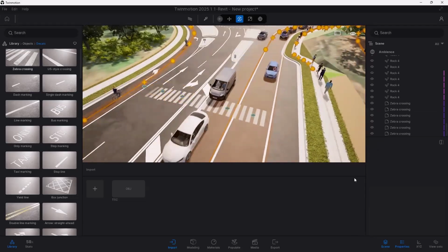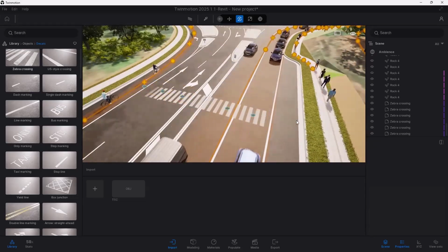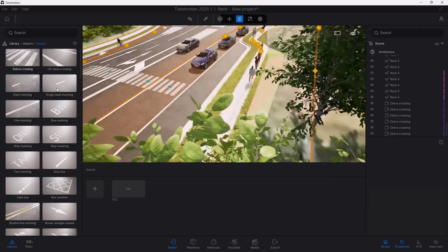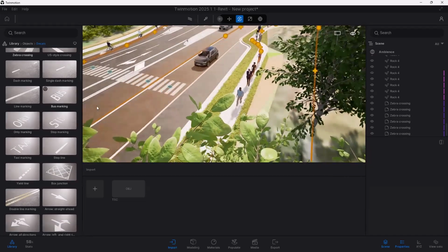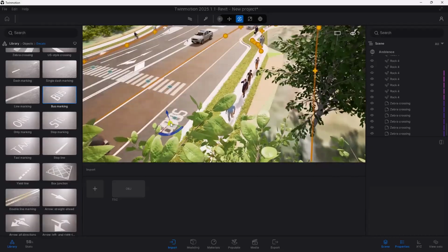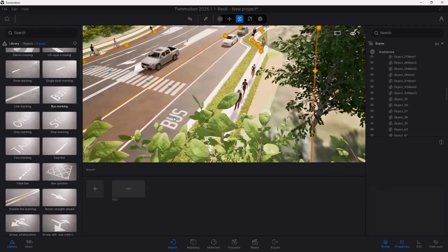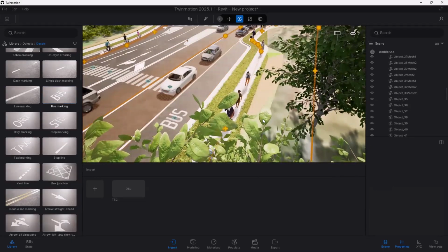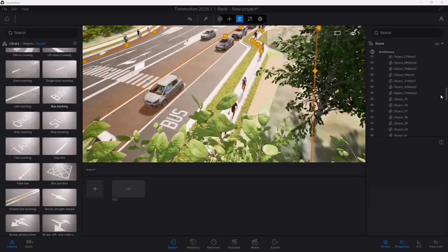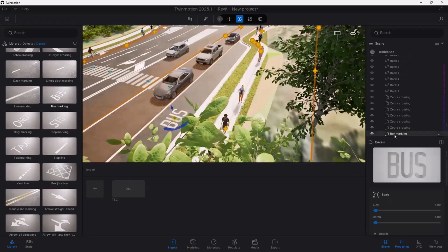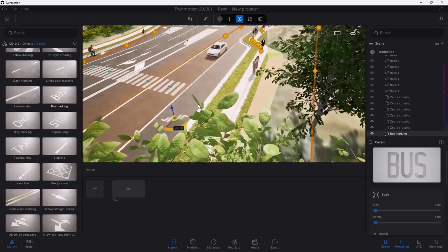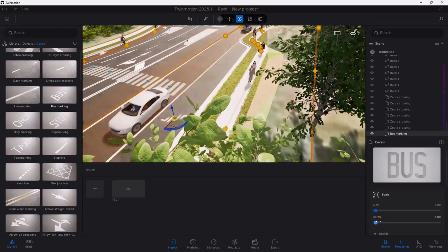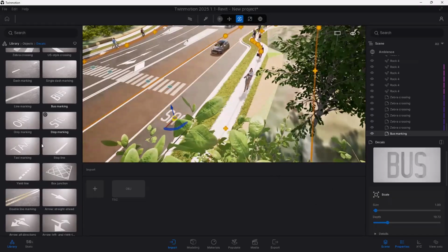So setting a depth is important for when you rotate. But if we ever think about the decals, cheap and cheerful, you can put in some marking here for a bus. You'll see about the depth here when I rotate this object, right? So if I find that bus down here, bus marking, rotate that, you'll see it starts to disappear. You do need to increase the depth as you cut through.